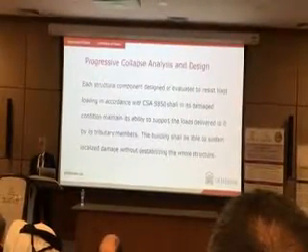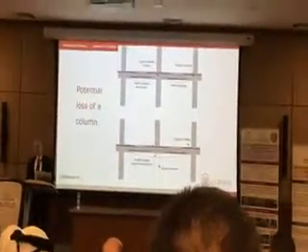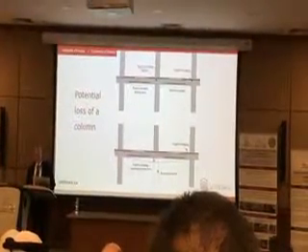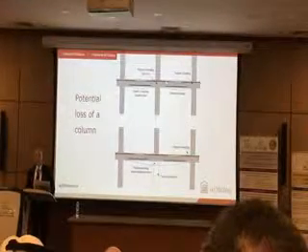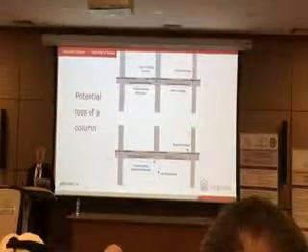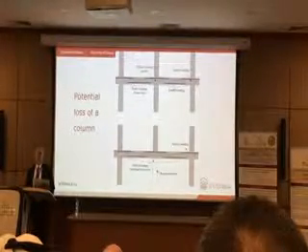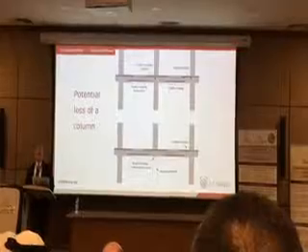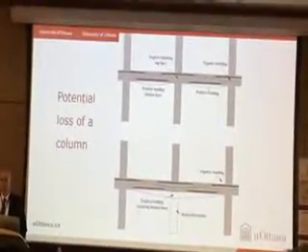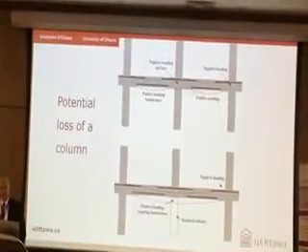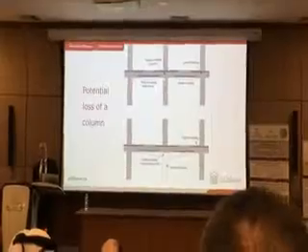That's what progressive collapse is. And this is typically done by removing columns. Now here at the top, you have an ordinary building. As you all know, we have negative reinforcement for negative moment at the top, positive reinforcement for positive bending, and even though sometimes we continue down, theoretically, all we need is here, and you may not have sufficient positive steel in the negative moment region.